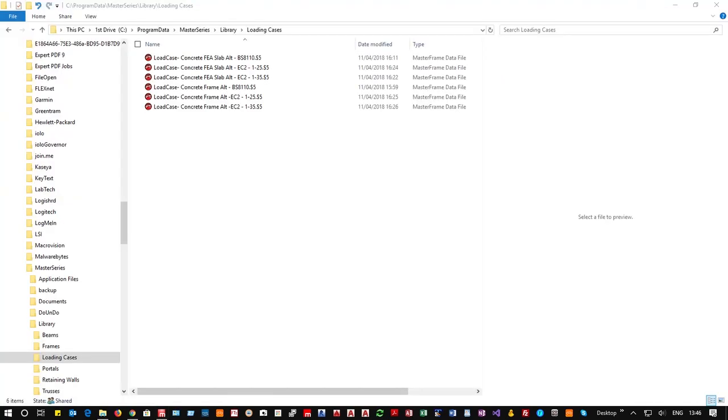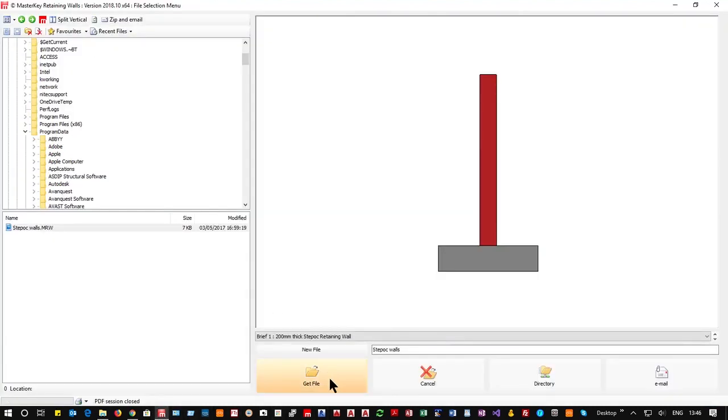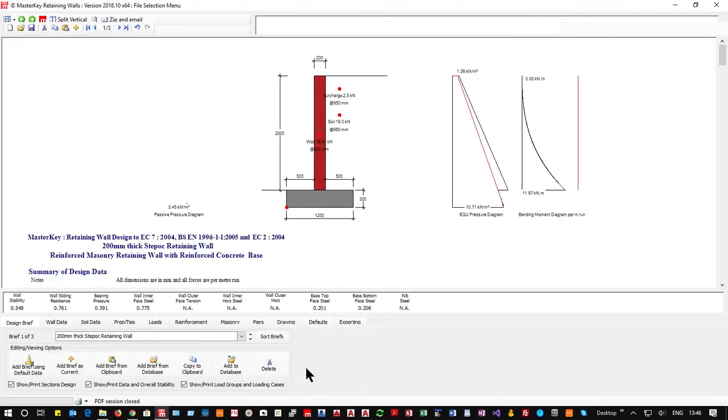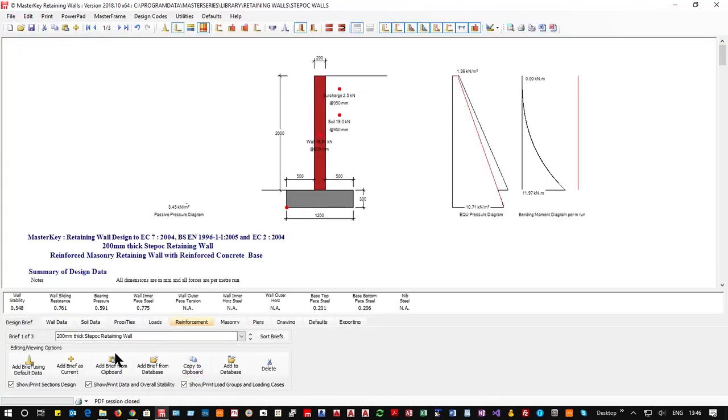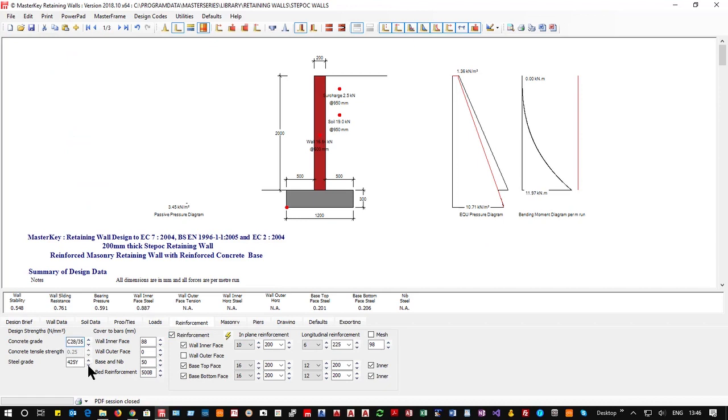Is there a way to create your own reinforcement rebar strength? Good question. Very good question. Obviously, inside any of these, you only have access to what we have set as our rebar. So we have the 425. Some of our African nations are still using that weaker 425. Likewise, I think the 460 was there, but it's been taken out, thank goodness. So those are all you have.